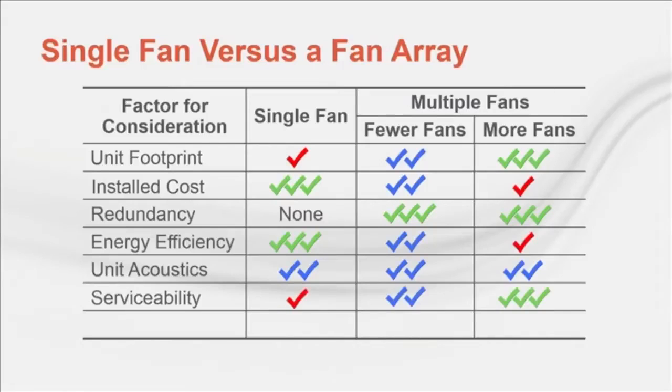Another benefit of using a fan array is easier serviceability. When multiple smaller fans are used in an array, the fans and motors are lighter and easier to replace, if ever necessary. Fewer moving parts, and therefore fewer fans, generally results in better reliability. Of course, the redundancy provided by using multiple fans partially offsets the concern over a fan failing.